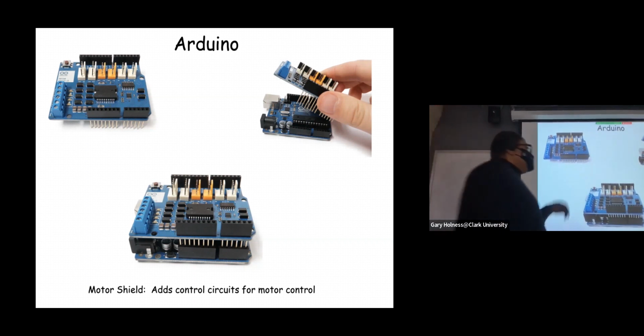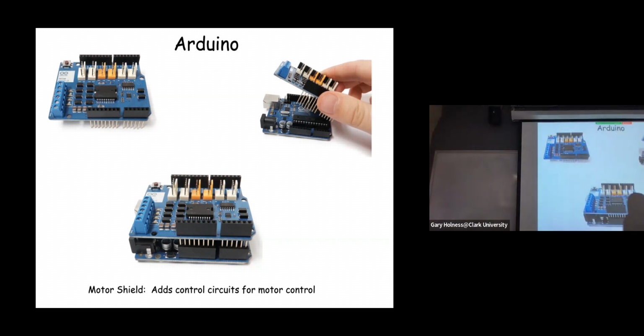And so one of the things we'll talk about is PWM, or pulse width modulation. But when you do that, well, of course, you have to turn on and turn off your signal on the board yourself in software. But with the motor control board, you just say, give me this duty cycle in PWM, and we'll talk about what that means later in a future module, and it will do it for you, right? So something that you'd have to implement in software, this motor controller board does for you just by giving it a simpler command, okay?